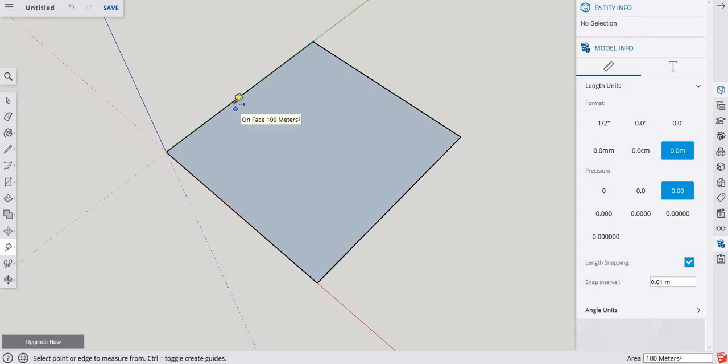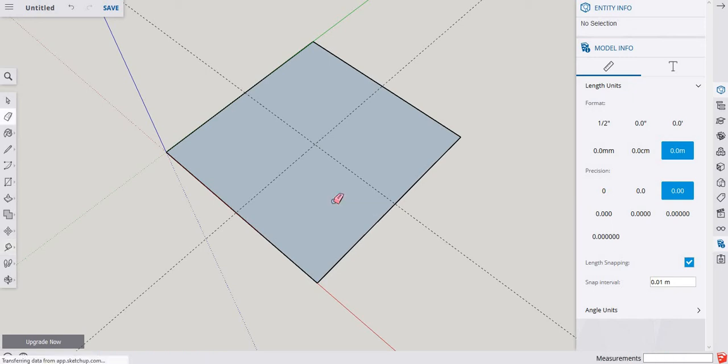Now speaking of guides, if you hover over a line, left click and hold and drag, hit the right arrow key, you can see how you can make this guide. I'm going to type in 5. Now it puts a guide right at the center point. Also, if you want to do center point, left click drag, and right there with that little blue dot, it'll do midpoint. So now we have a perfect intersection point. Guides are extremely important if you're going to make precise parts.